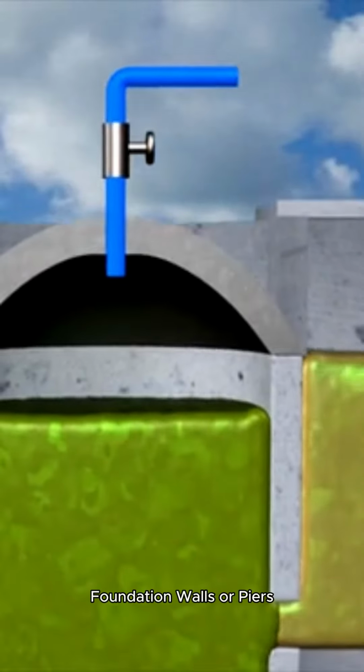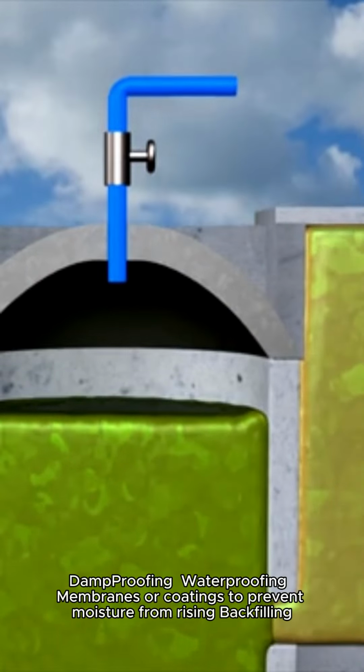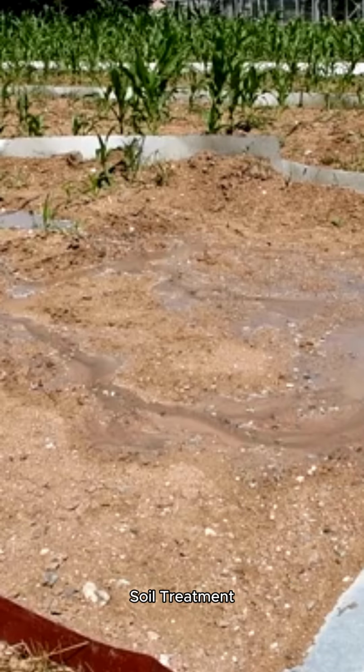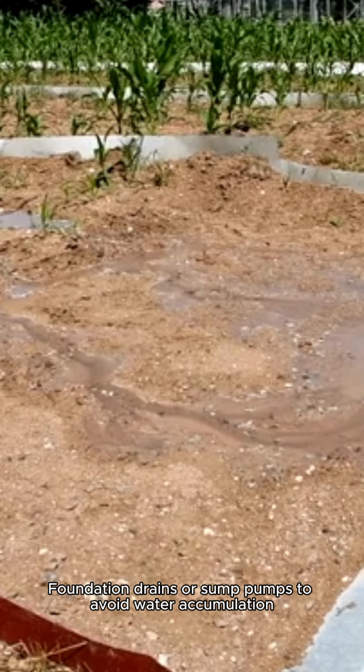Foundation walls or piers support the superstructure above. Damp proofing and waterproofing: membranes or coatings to prevent moisture from rising. Backfilling: replacing soil around the foundation after construction. Soil treatment, to prevent termites or improve bearing capacity. Drainage systems: foundation drains or sump pumps to avoid water accumulation.